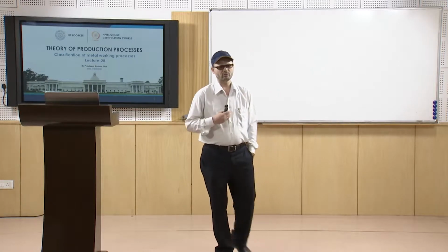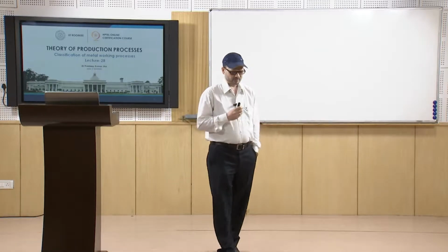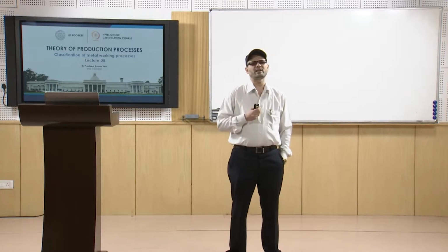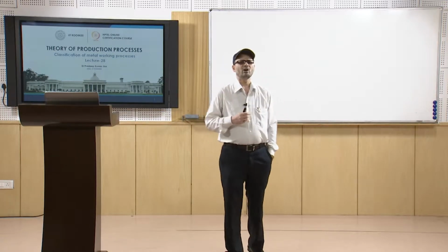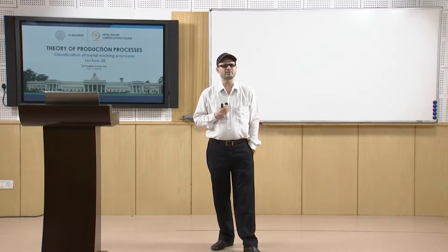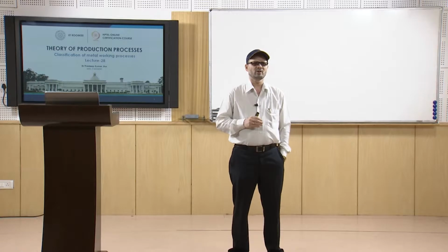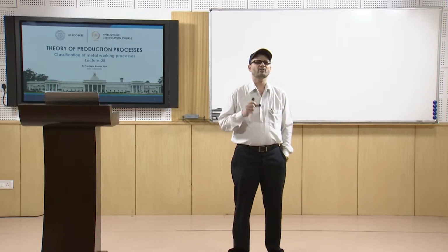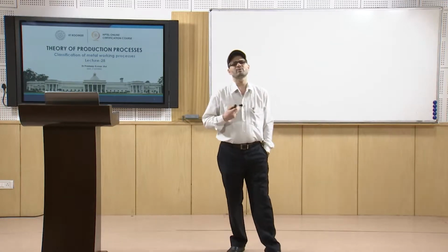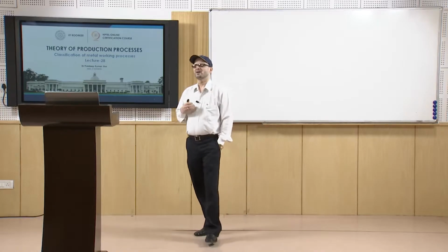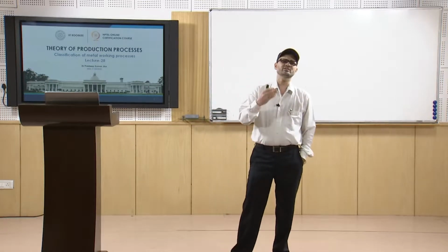We are hopefully aware that during casting you get defects like blowholes, air inclusions or so, and many a times you need to have specific properties. So, what you do is you work the metal. You work the metal for controlling some of its mechanical properties, for imparting certain mechanical properties which you specially desire to have. So, that is why these metalworking operations are important.